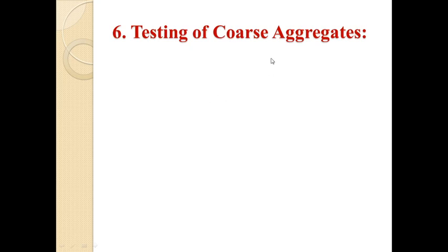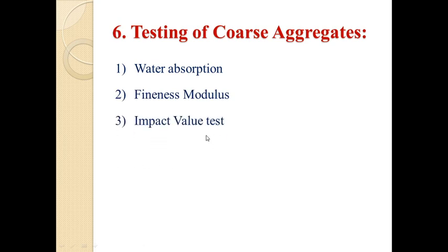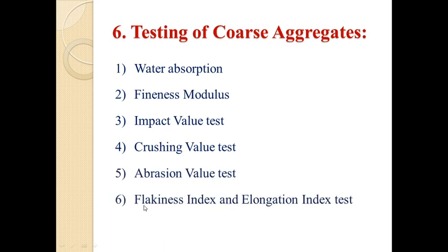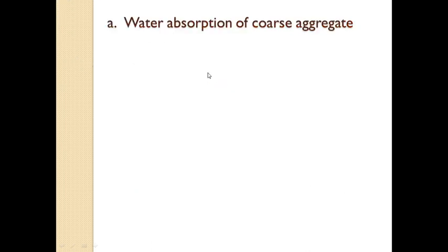Next is the testing of coarse aggregate. So what are the tests conducted on the coarse aggregate? Let us see. First, water absorption. Second, fineness modulus. Third, impact value test. Fourth, crushing value test. Fifth, abrasion value test. And lastly, flakiness index and elongation index test. So let us see first the water absorption of coarse aggregate.